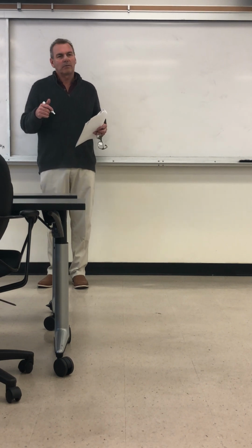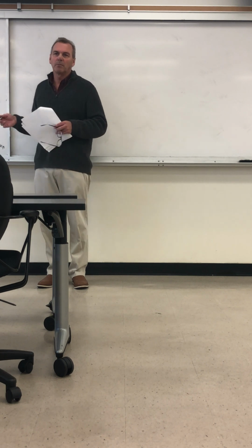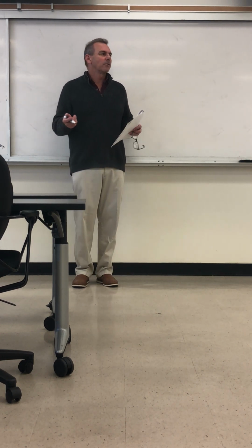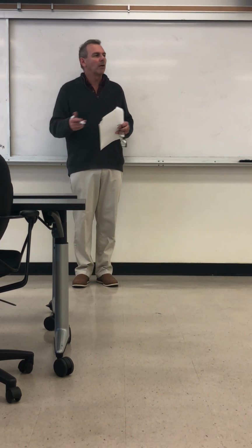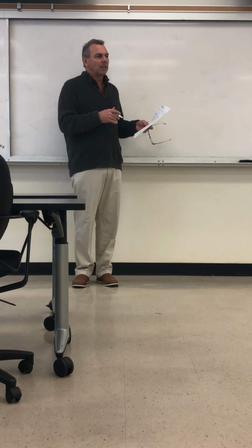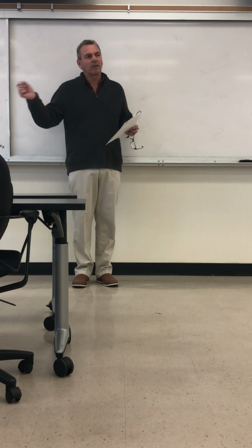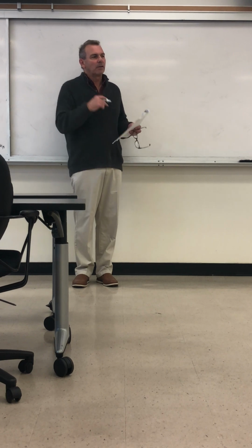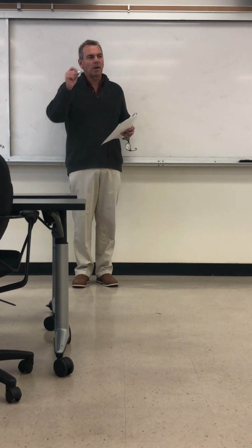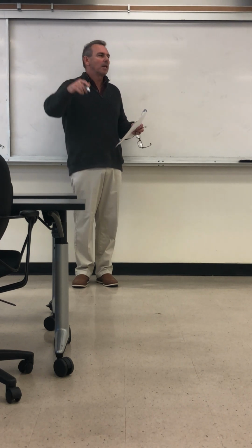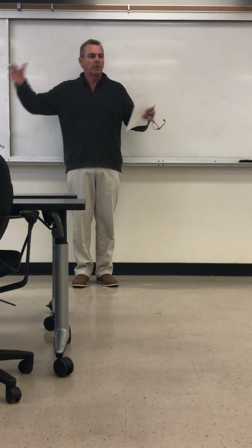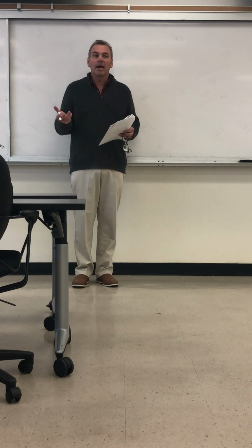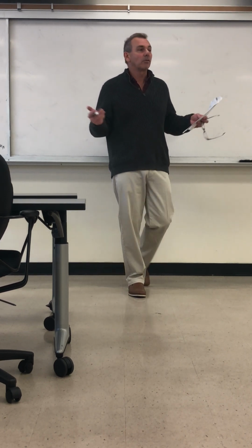I teach you methods for solving problems by hand, not just jumping on the computer. And you get the same results as the computer, so it's important to understand that. Whenever I've designed structures or done analysis or retrofitted structures, I always verify. Sometimes I've designed structures, complete bridge structures, even large structures, by hand calculation, and then I checked it by computer. Typically, you design it by computer and you check the results by hand calculations, spot checking results for the longer span, the maximum and minimum in the span, maximum axial force in the column under different loading cases, things like that. Spot check 10 or 20 results, and you're getting 99% the same result as the computer program. You can get closer if you want, but that's good enough.